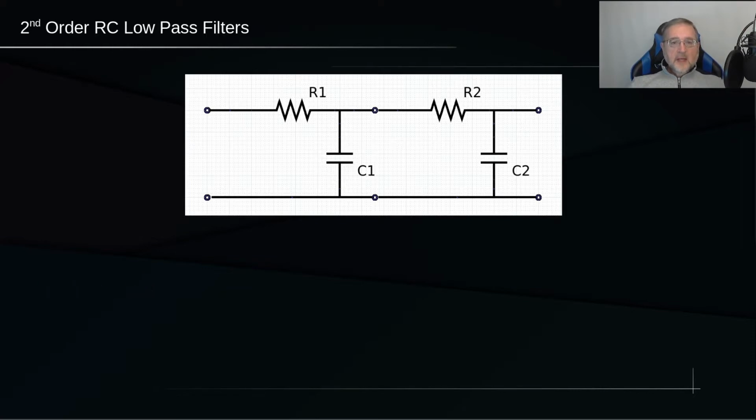For the experiment, and to have something to use as a reference, I have used the same exact components from the previous video. A 10 kΩ resistor and a 1 nanofarad capacitor. We will check out first how the output voltage changes with the frequency, both in amplitude and in phase, and then we will measure the cutoff frequency, and finally the infamous attenuation rate.